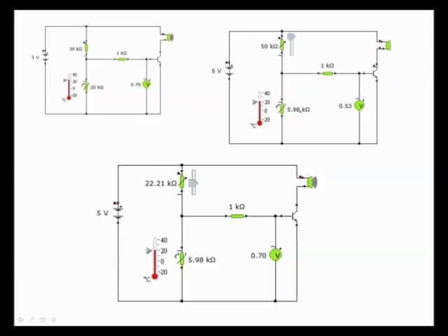And what we could do is we can replace this solid resistor up here, so just a standard resistor, with a variable resistor. So if I make this a variable resistor, this one goes from 50k up here down to about 1k down there. I can change the resistance on this easily and get this buzzer to switch on and off at the temperature I want it to.